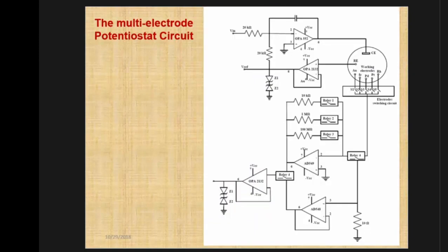And this is the sensor signal conditioning circuit. This is the part from where the digital to analog converter produces the voltage, and then it is applied to the electrochemical cell. The interesting part is that the electrochemical cell actually is a part of this feedback loop, where the property of the solution gets embedded inside this control amplifier. Whenever a voltage potential is applied, a profile of voltage is applied, the corresponding chemical reactions, which are dynamic in nature, are converted into a voltage signal through this I2V converter, which is again a gain selective network.